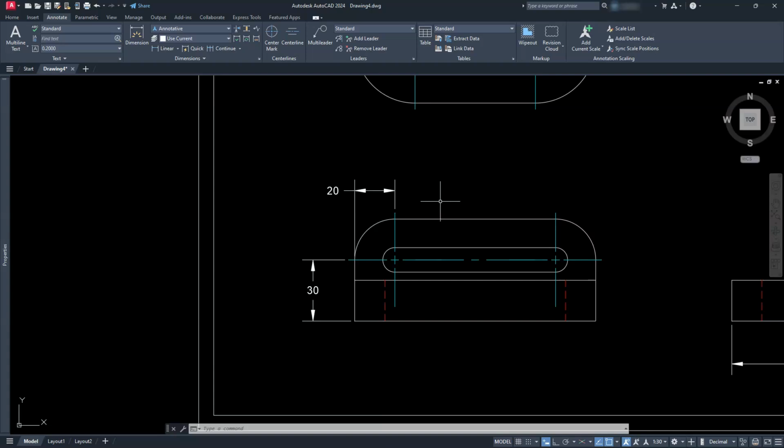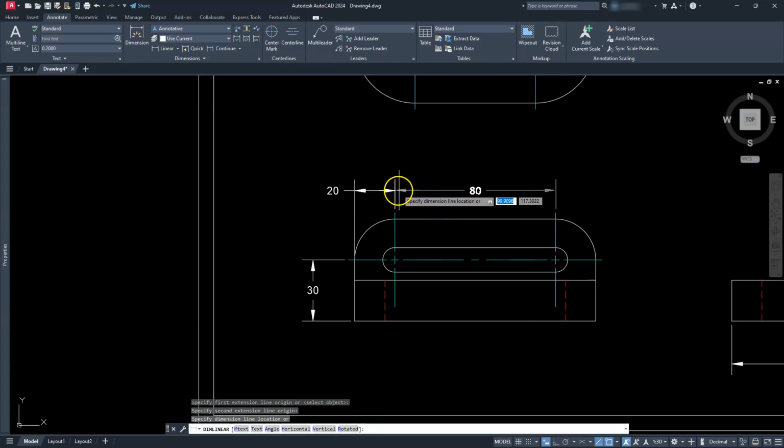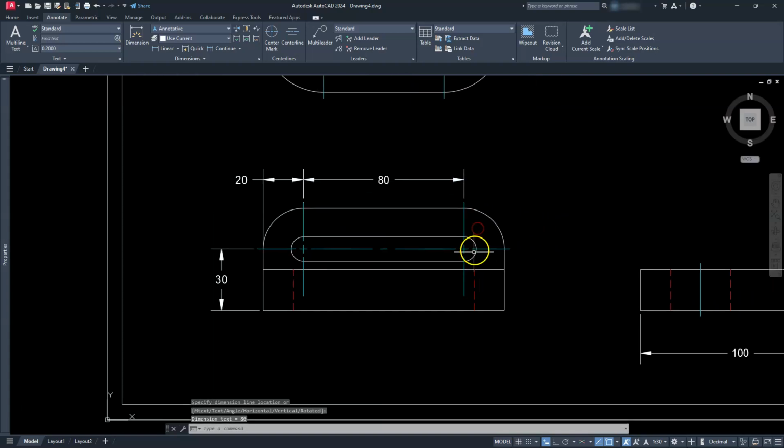If you use Inventor, it works backwards from that. So that's one of those things you've got to remember. Go back to the linear option. I'm just going to select that endpoint to this endpoint and go ahead and place it right on that endpoint. Okay? Let's go ahead and knock out both of the radii that are on here.